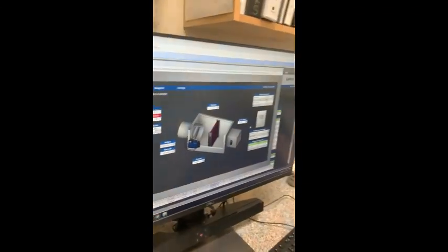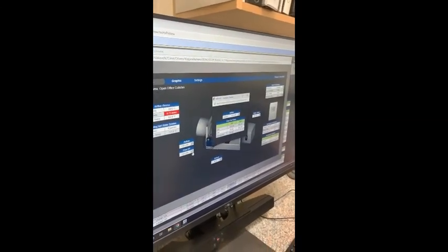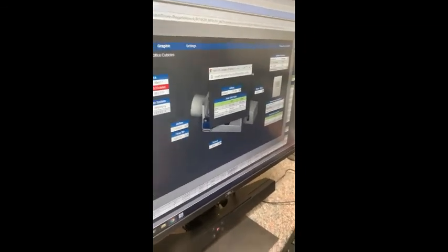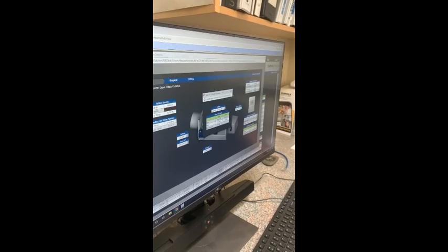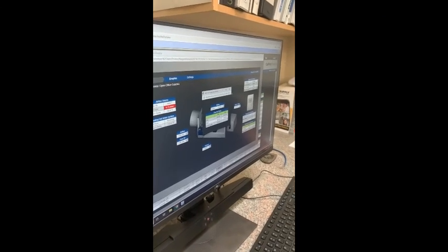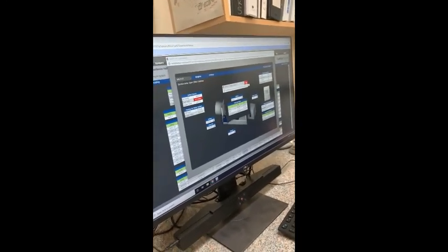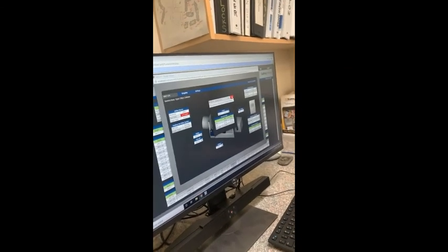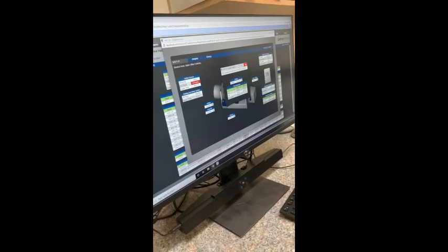So if someone changes the airflow set point on this, is there any kind of designation on that? Is there any kind of designation on the unit too of that airflow or anything? Not that I'm aware of, because really it's more the box size that determines its flow scale. But sometimes it can be really maxed out, and other times it can be barely using any of it.